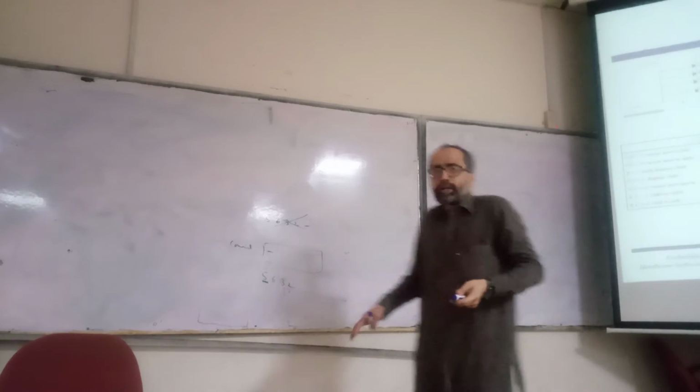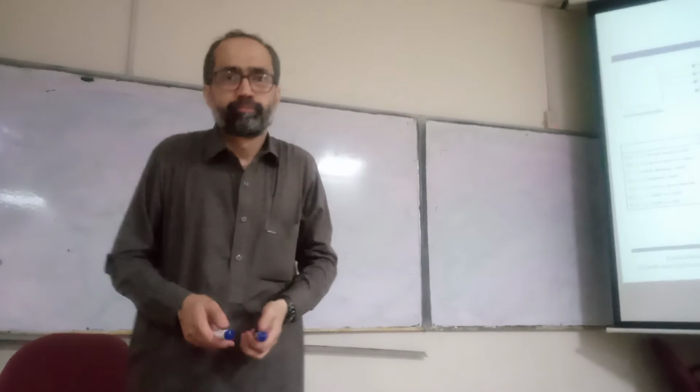It is return cursor home. स्टेरिक का डोंट केयर कंडीशन मतलब है सर? Don't care. You can send a logical 1 or logical 0, doesn't matter. ठीक है सर। Don't care. Even if you send 0 or 1, doesn't matter. It will return cursor home. Okay. Now if you look at this signal, the value of DB2 is 1.